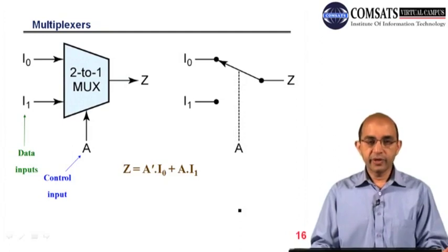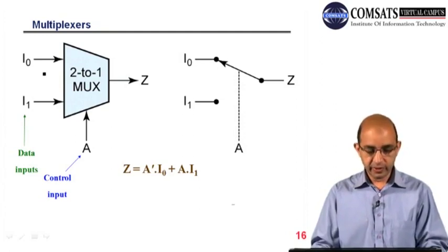And then we can use multiplexers in order to design a D latch. So let's talk about multiplexer. This is a 2-into-1 multiplexer. We have 2 inputs, 1 control signal and 1 output. As we have 1 control input, we can have only 2 values. When A is 0, that means I0 will be selected. When A is 1, I1 will be selected.